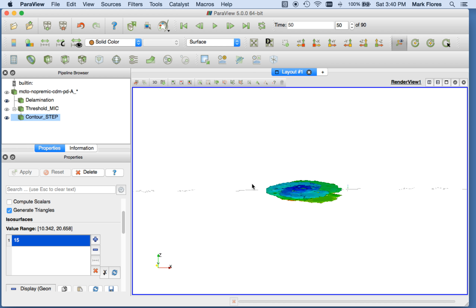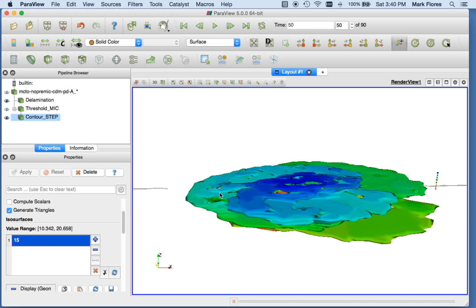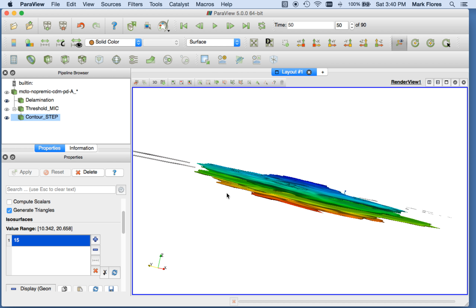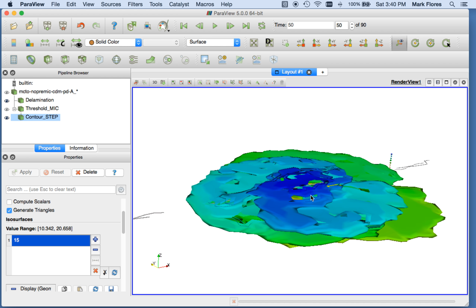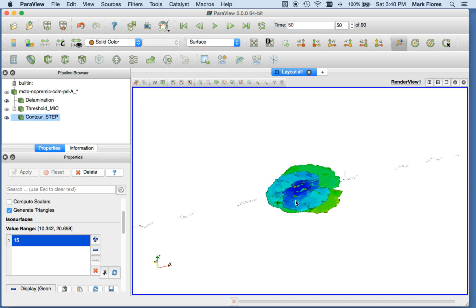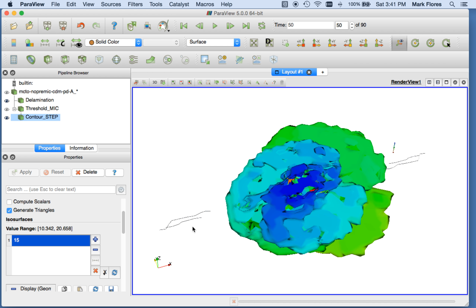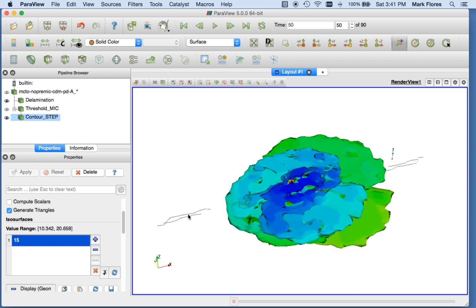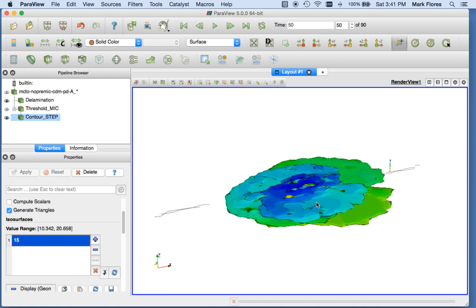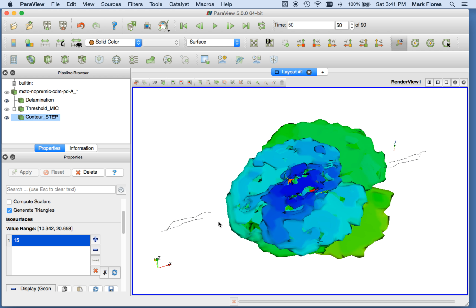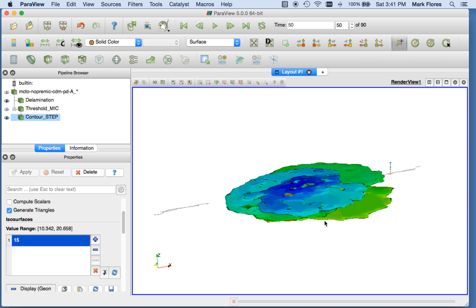So you kind of see that there's cracks, and this is volumetric, so you see what sort of ply they're on, and you see where they're occurring. The reason why they're kind of funky is because of the discretization of the model. This is a 0 degree transverse matrix crack. So the curvature of this is not a reflection of the actual fiber. It's just a discretization of the model.